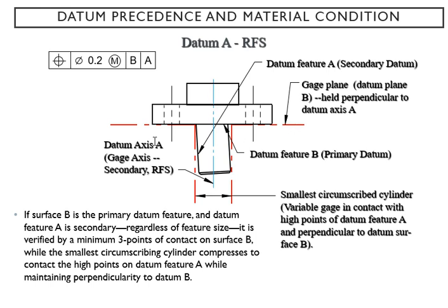The red one is your gauge plane, and the gauge axis is right here along with your datum axis A, because we're using a gauge to establish the axis of A, so the gauge axis is about the same as your datum axis A. Of course, when you're establishing that, you know that you have about 3 high points for B in contact with the gauge. Those have to come automatically in your head, all right?